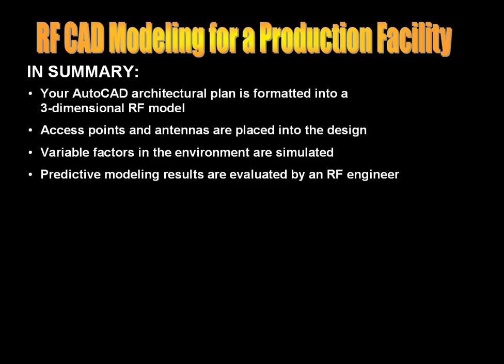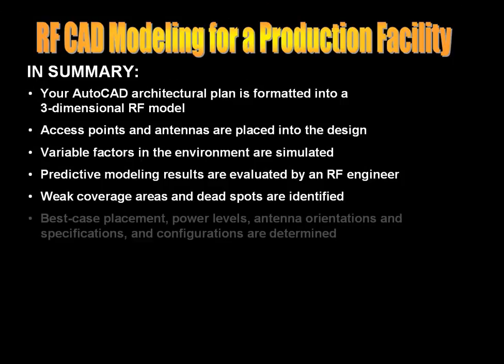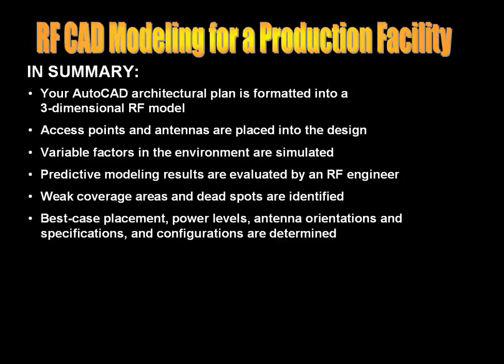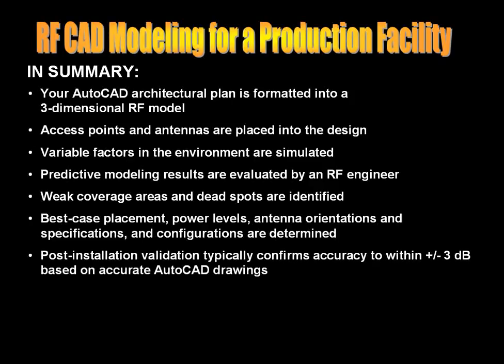The RF engineer has the luxury of moving things around, reconfiguring things in the virtual space. In this way, when weak coverage areas or areas of concerns are identified, they can then be focused on in an on-site engagement. But because of the accuracy of the CAD modeling, the correct configuration and best placement of the equipment is almost always identified in the model. We find that post-installation validation typically confirms accuracy to within plus or minus 3 dB or better, based on how accurate the AutoCAD drawings are.